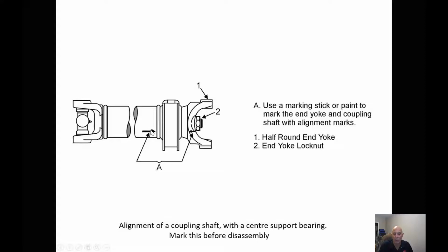So make sure that before you take this apart to replace this steady bearing, that you do mark it, take it apart, and make sure you put it back in phase.